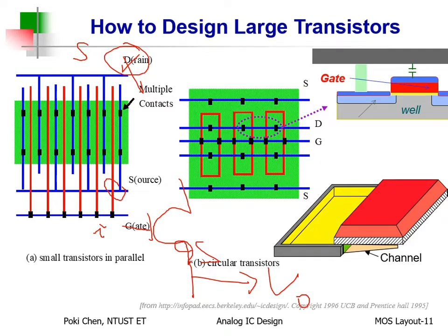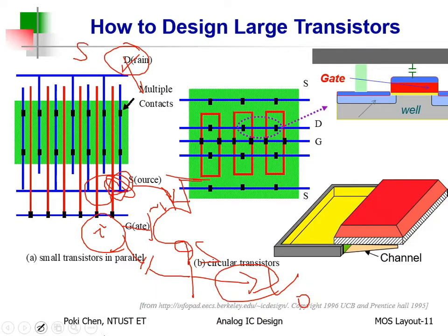Okay? Yeah. But you may be curious, hey, how about the parasitic there if I am there just like here, right? I will get more parasitic capacitance. No worry. This is the common node, right? Input here, output is there. We try to reduce the parasitic between your input and output. Why? According to the Miller effect. Got it?